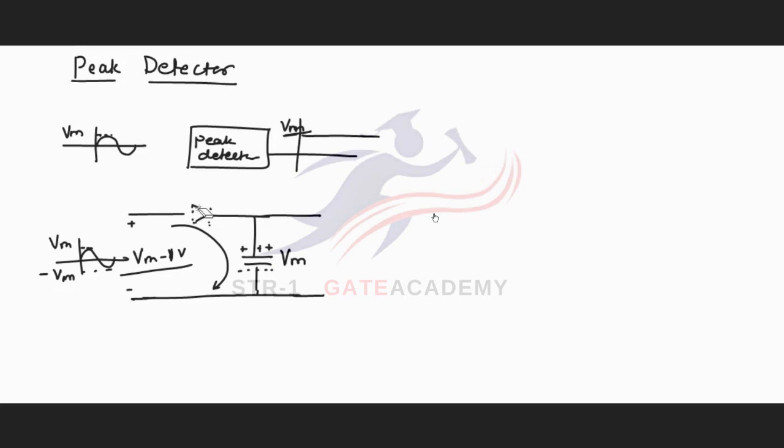The diode will be reverse biased and it will be replaced with an open circuit. Now we can see that the input is disconnected from this circuit and the output is equal to the constant Vm.